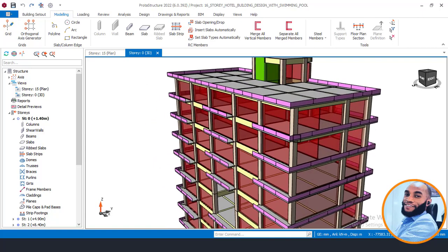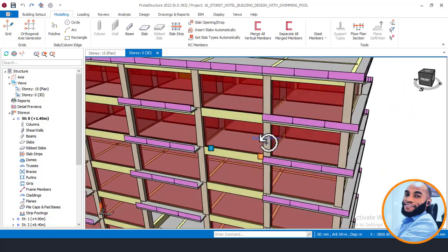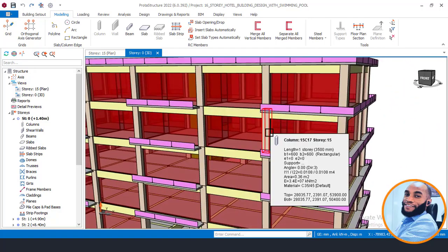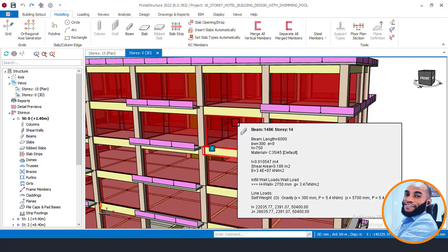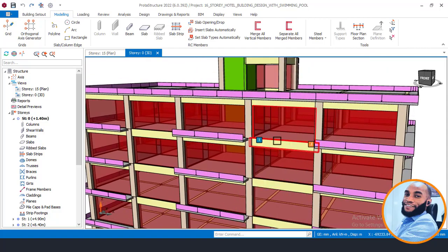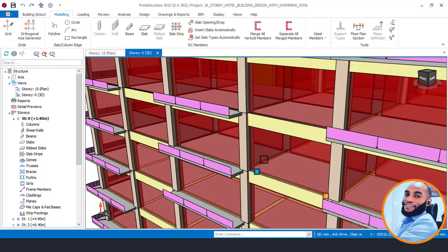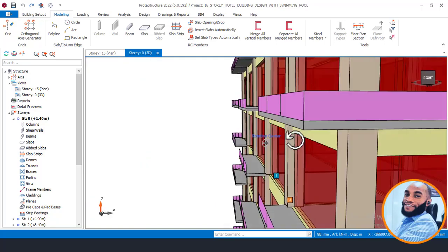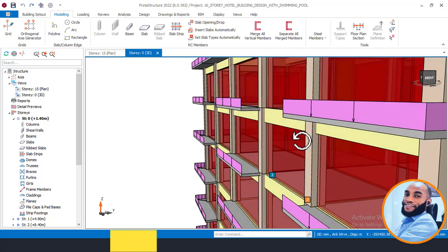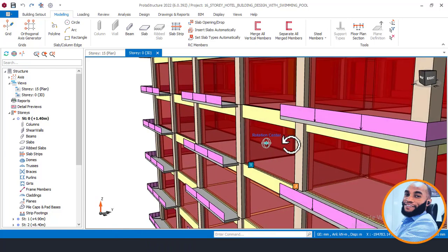But now that we are designing for a hotel building, it won't be nice to go and use, let me say, a wooden board to separate rooms. That is not safe. So I think we will still use block work for these partitions between rooms. Okay. Now knowing that the block work method used to reduce load is not going to work on this hotel building,